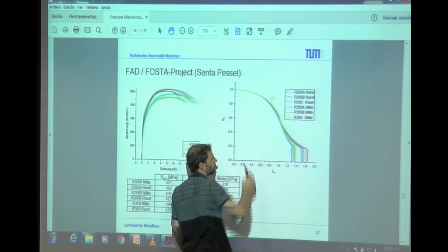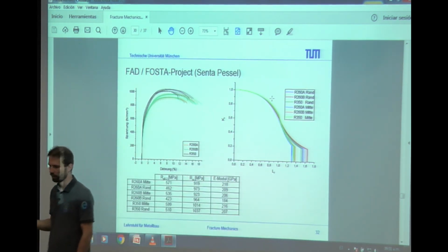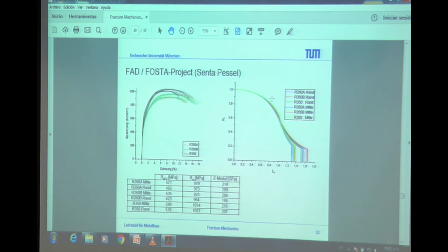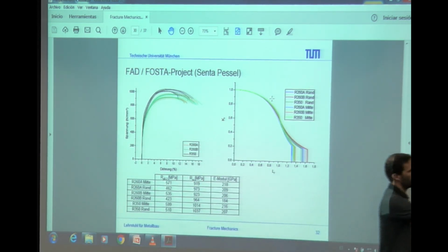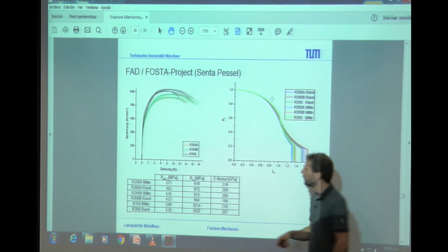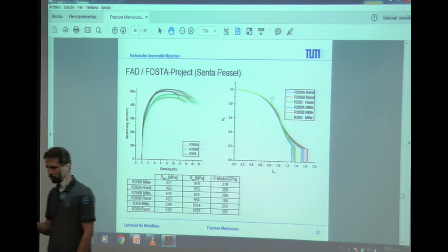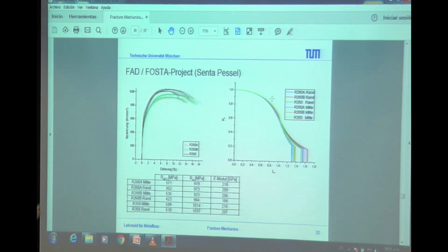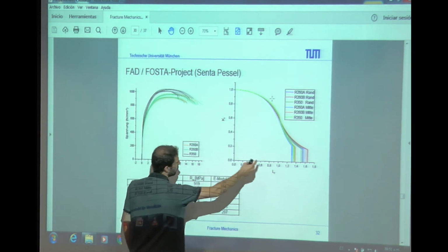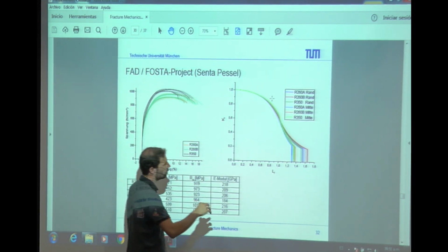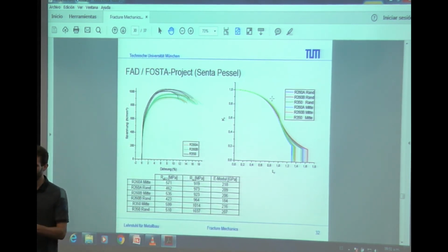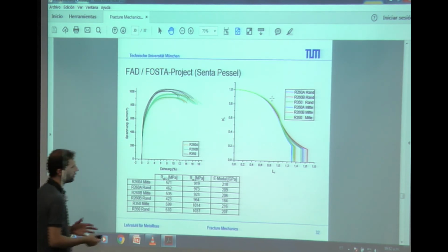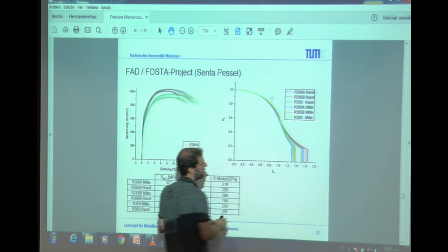But of course, for the fracture mechanics, so for the definition of the crack, of the K1C, she also had to conduct some fracture mechanics testing to describe at the next level the K1C and the J1C. But just by using the information of the tension test, it was already possible to go into the diagram and to get the basic information on where there is some yielding and where there is some enhancement, for example, next to the plastic collapse.